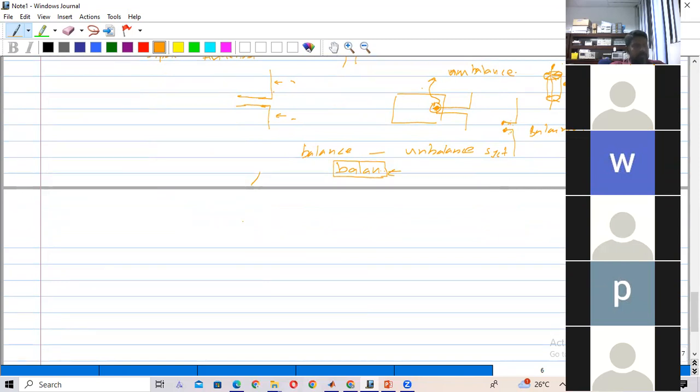In Dialog TV you are using a parabolic antenna, and there is a feeder like this, and this feeder is connected to the line. There is a reflector, and the ground is also connected. That is a coaxial cable, and the other end of the coaxial cable is equipped with a BNC connector. You can directly connect this BNC connector to your Dialog TV decoder, or satellite TV decoder.